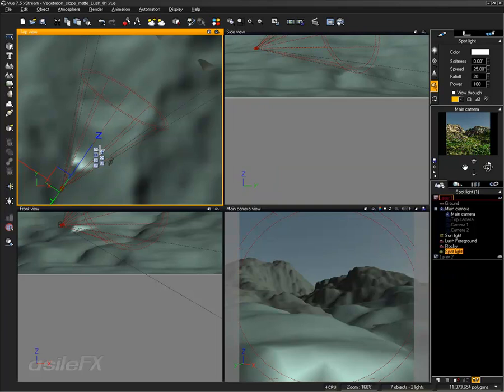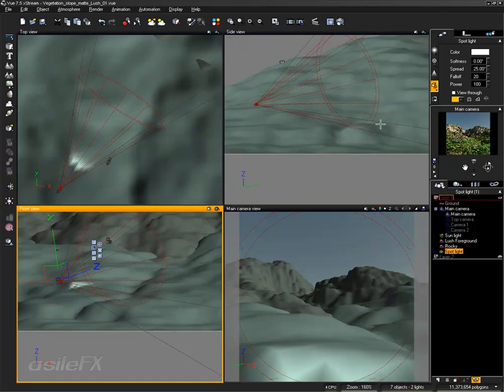the camera bounds, you can adjust the spread, which is currently a degree amount, to match the camera focal. So you can set up an equation to calculate between spread degree amount and focal length if you used this method a lot. Currently, I don't have any sort of calculation like that.